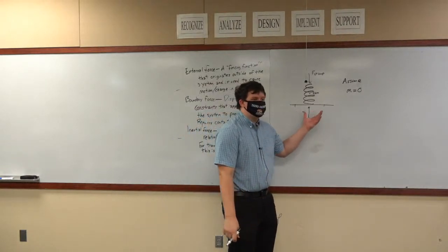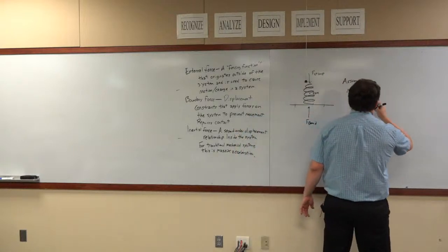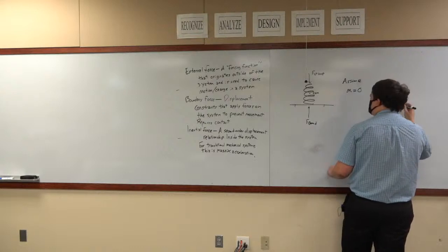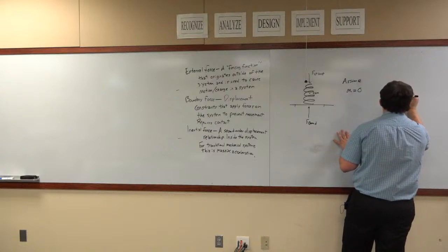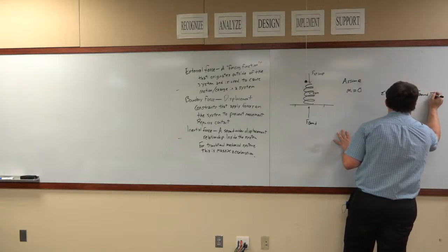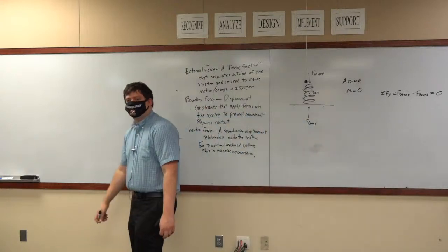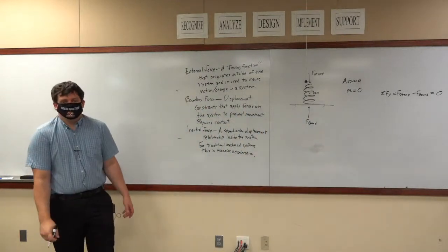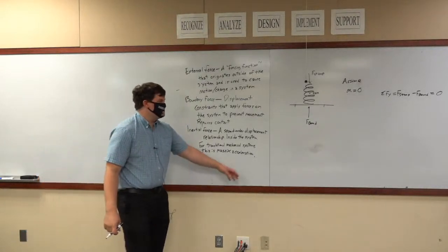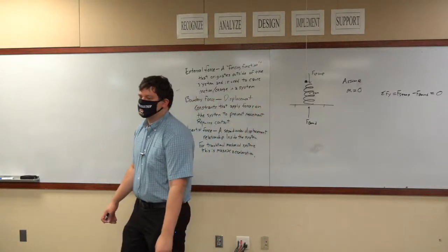Now looking at it from a system relationship, if we do all of our external forces, sum of the forces in the y direction is equal to F stamp minus F bound, that's equal to 0. We have no movement. Well, we do, but the movement doesn't change anything. You have a direct relationship between the boundary and the stamp force. You don't have an inertial force anymore.